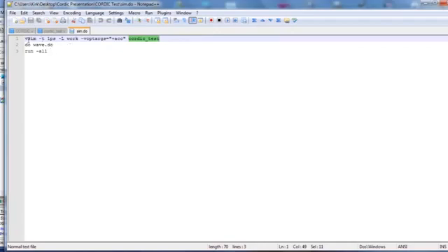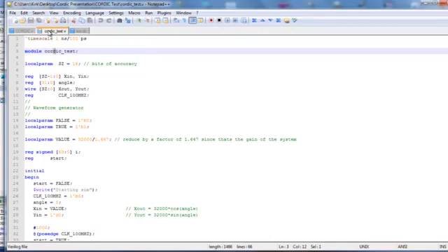Let's first look at this script here. Basically, all this does is invoke the simulator with some arguments and start with our top level module, which is coordinate_test. It also has some signals set up in a waveform that you'll be able to see, and then just tells it to run it. Let's look first at the coordinate_test.v. This is a stimulus file, a behavioral model to simulate driving the input of our coordinate.v module.